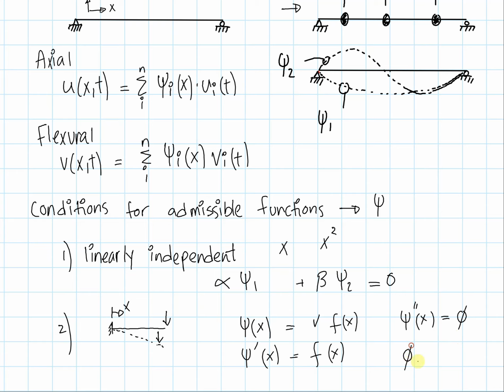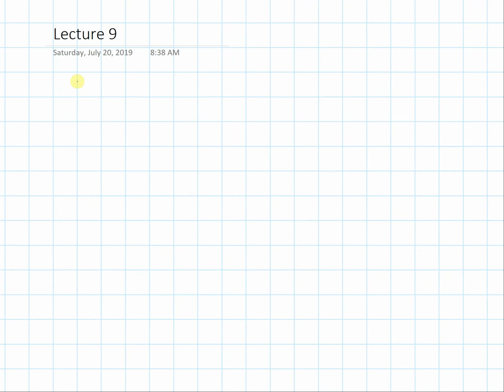Now, curvature is proportional to the moment divided by the elastic modulus and the moment of inertia. Now, if I have a loading setup which results in a moment that is not constant or that is not zero, then I need to have a mode shape that describes that kind of curvature. So let's think about this. Let's say I have psi that is equal to (x/L) cubed.